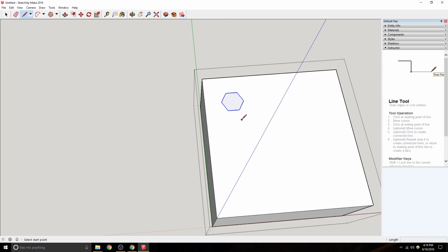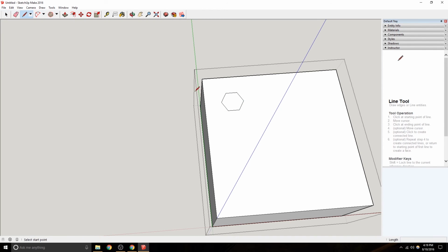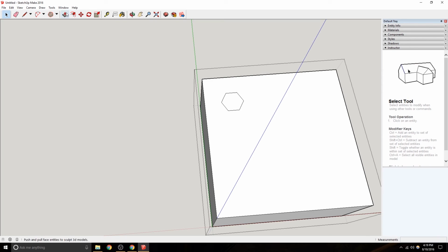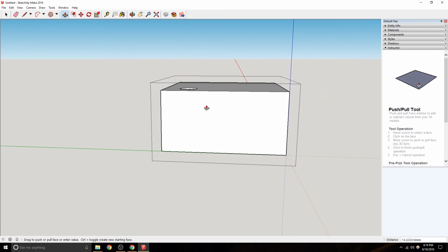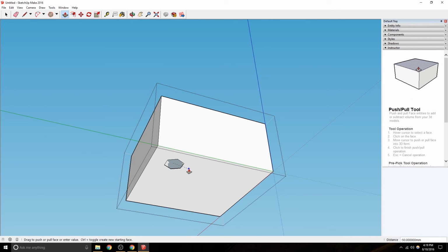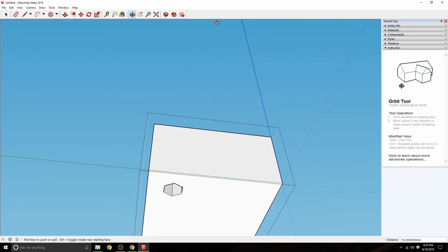If you want to check that, what you can do is hold on the edge. If you hold on to the edge of this design, this polygon, it'll show you the center point. From here you can measure. You'll see down here in the bottom corner it says 20. This one says 20, so we know we're good. Alright, so through hole, again, you're looking at an extrusion. There's other ways to do it, but that's probably the simplest. And then you just snap it to the face. It should be pretty clean for the most part.